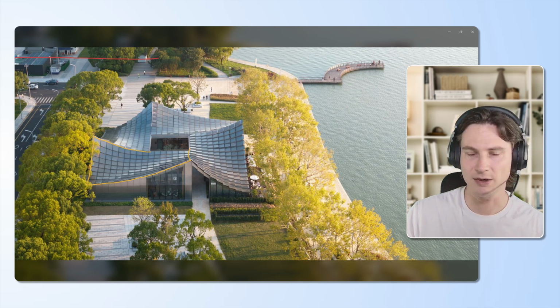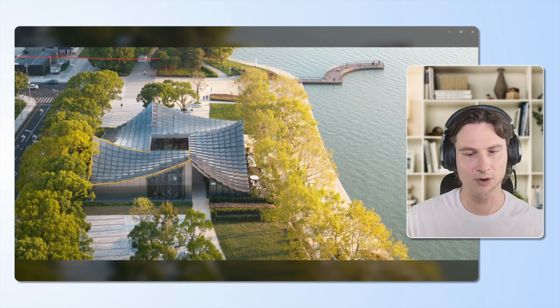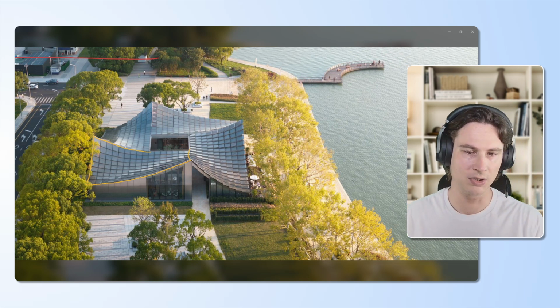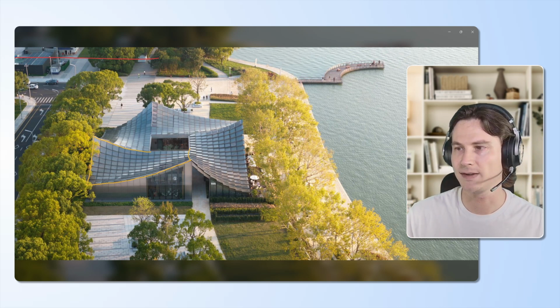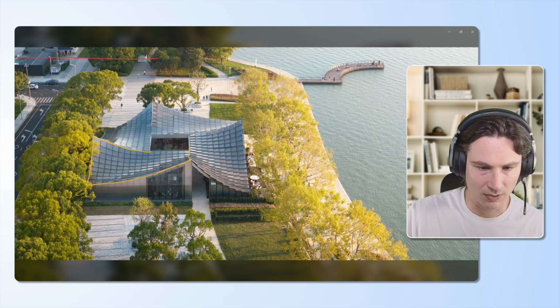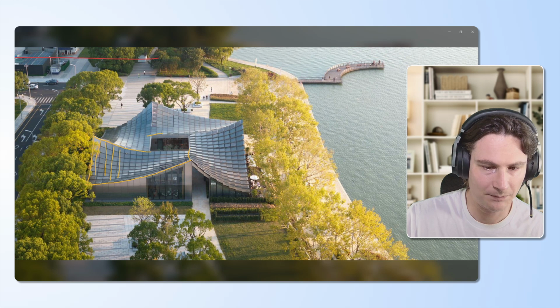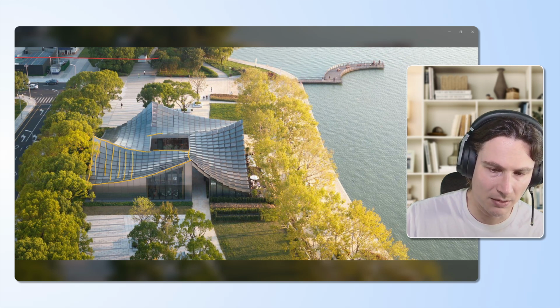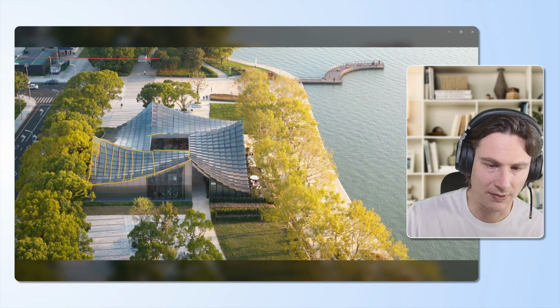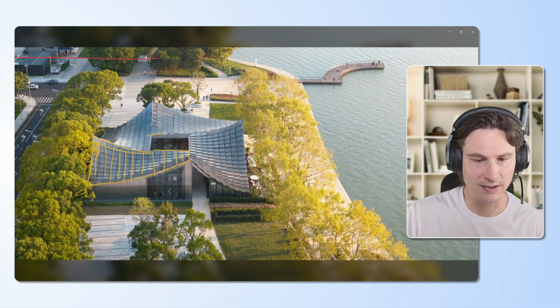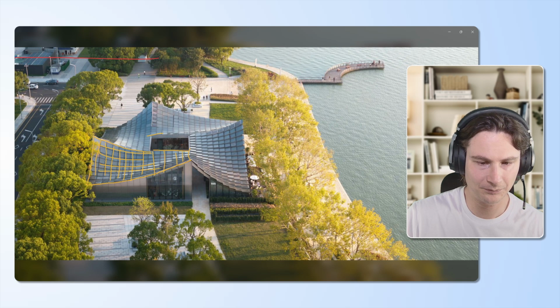So that's basically what's happening here. It's a simple setup using those 4 boundary curves to create this smooth catenary surface. And then if we go again here, this is the panels. So when we have the surface, well, this is a straight line, but if we have the surface set up, we'll take a look into how to create the individual elements basically.